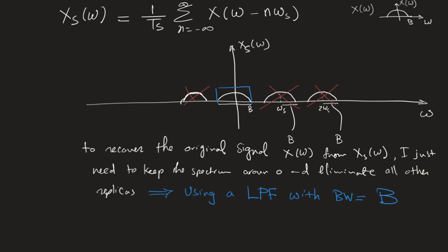I'm going to draw an explanation for this. This is the operation when you have a pulse put into your circuit or your filter, and then another pulse. The filter cannot trace the pulse. It's going to try to move smoothly from one pulse to the other because it's a low-pass filter. It just doesn't change abruptly. It will keep changing slowly. And this effectively is an interpolation process, which is going to recover a continuous signal from the sampled signal, okay? If you meet the condition. Now let's look at the condition.